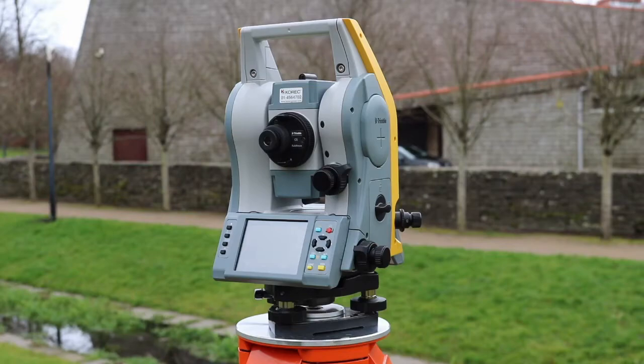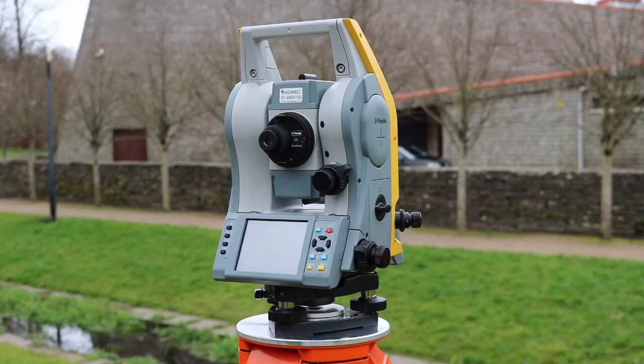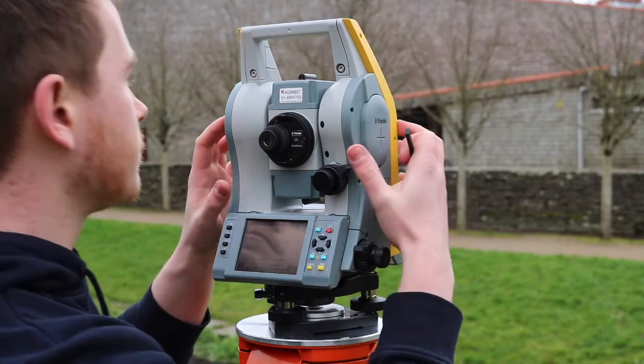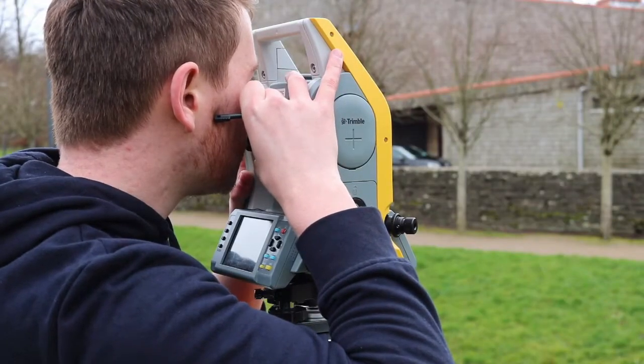Once this is done, you must backsight to the control point in question. Move the machine's telescope to within a reasonable distance from the control point. You do this by using the optical sight on the very top of the machine. This allows you to place the telescope in the general area of the control point. This method allows you to quickly locate and hence shoot the control point accurately.